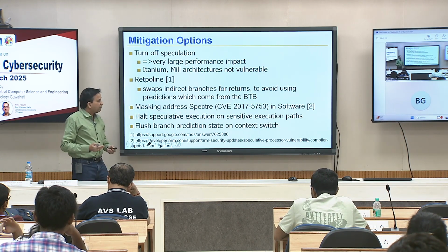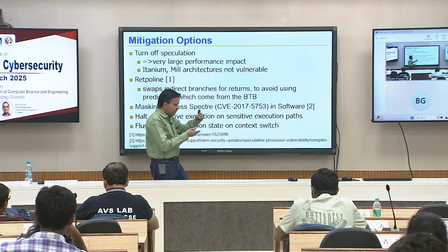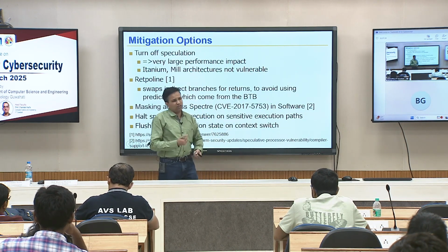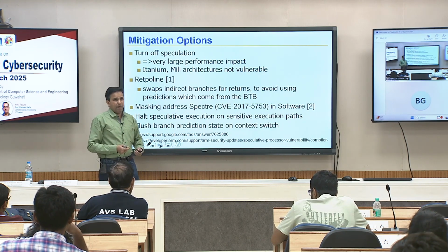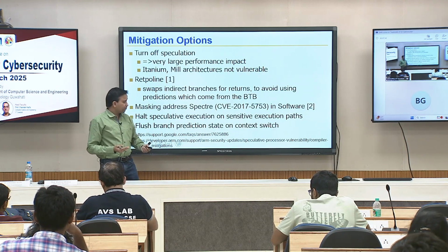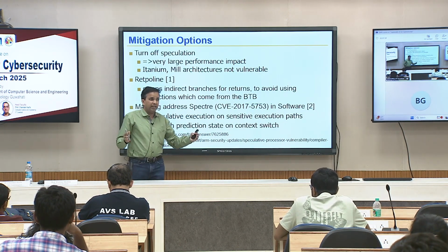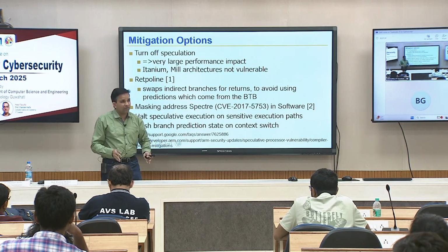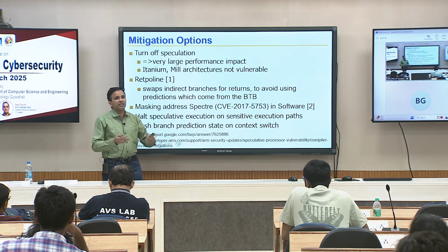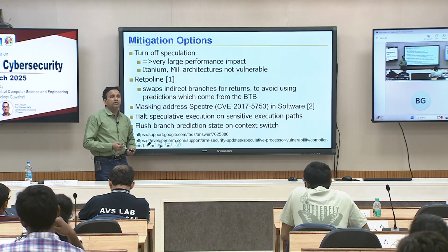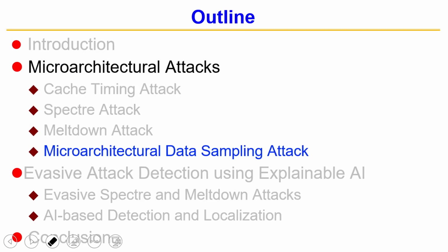But flushing the branch target buffer, which maintains history information, is possible, it is typically 1024 entries, whereas flushing the cache is kind of impossible, it is megabytes to gigabytes of space, and on every misprediction. Remember the pipeline is very deep, branches are coming almost every alternate clock cycle, and even if you have a 10% misprediction, flushing takes hundreds to thousands of cycles. So, you can imagine how much performance penalty it is. So, that is about Spectre and Meltdown.